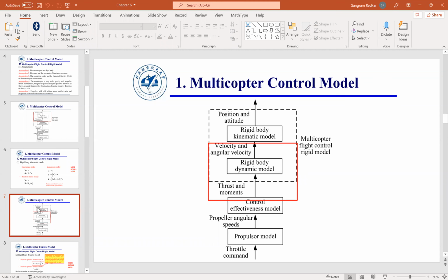Depending upon the aircraft that you are using, the forces and torques would change. Which means if you have a fixed-wing aircraft, you are going to have lift and drag of the aircraft wing, and you will have the drag of the aircraft body. If you have a quadcopter, you will usually ignore the lift and drag because of the prop. You only include the drag because of the quadcopter body.